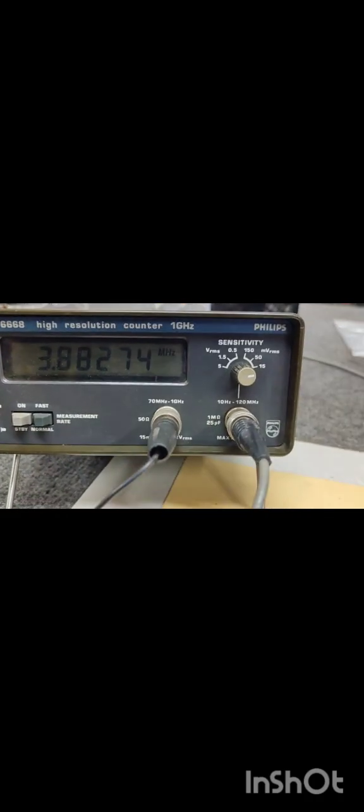It won't impede the operation of the microcontroller or any sort of timing circuit, because only the rising and the falling edges of the signal are actually used for timing. So it's not so critical. And even in a data sheet, you will see that it allows for the variation. This is very close to 4 megahertz for this type of ceramic resonator. So even this one here, it's 100%.